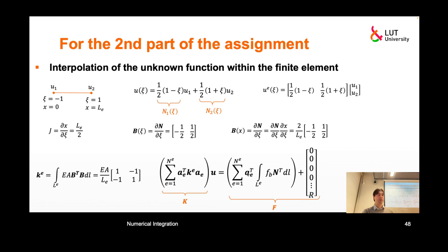The difference is that this time it's body force, but it's still similar because in that case, for the boundary condition, there was an integral over the face, that line, and now our entire body is just one line. In this case, the body force is an integral over the line, so it looks similar to what we had for boundary conditions there, but this is body load. In any case, they all end up in this right-hand side vector.